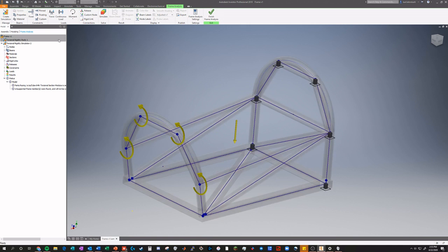Now you don't need to use any loads that are exact, like, down to a tenth, because you're going to be more concerned with the actual loads that are being seen in your chassis and how they perform relative to each other. As long as you've got some factor of safety, it's not going to be too important that you get some exact load.